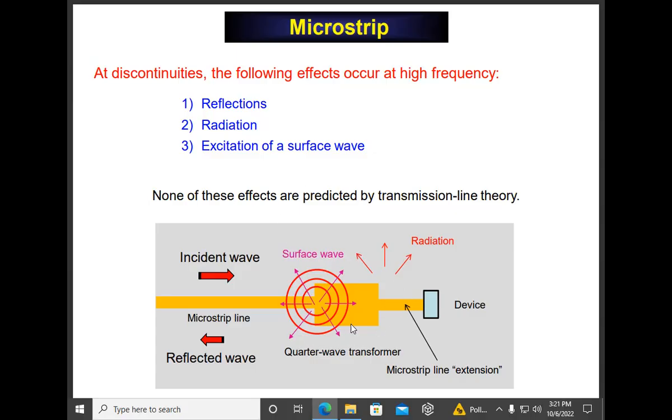We're using a microstrip quarter wave transformer to transform impedances. Now, it would be transforming voltages too, by the way. So in other words, if you calculate the voltage here and the voltage here, you would find that they would be different. It is acting as a voltage transformer, but we don't care about that. For impedance matching, we just focus on the impedance transforming properties of the transformer, right? In the power world, they care about the voltage transformation properties of the transformer. Okay, does that make sense?